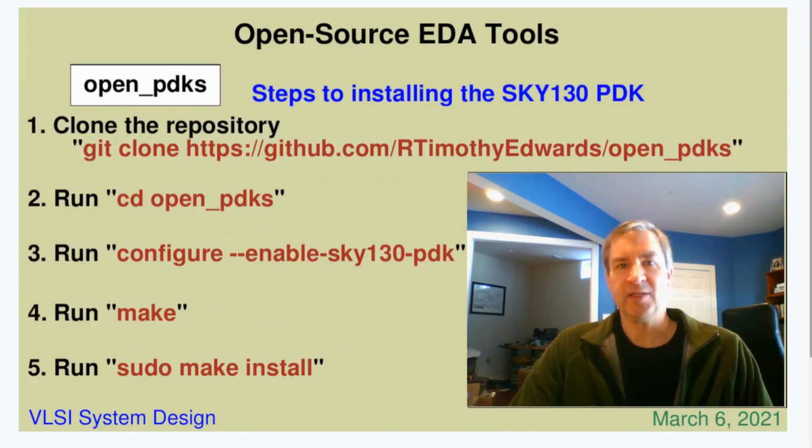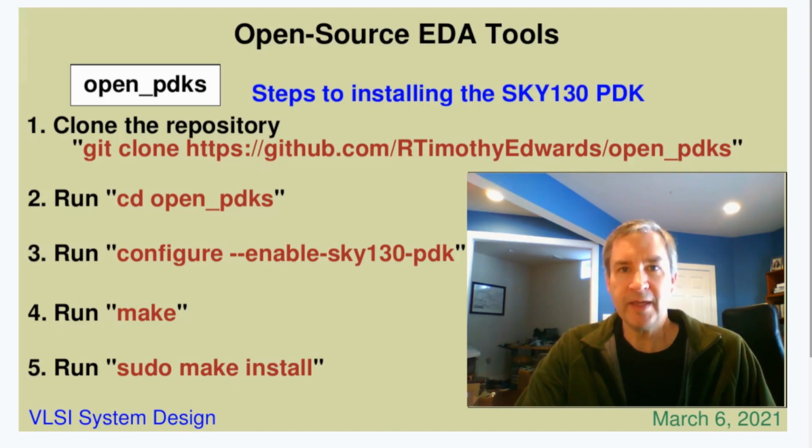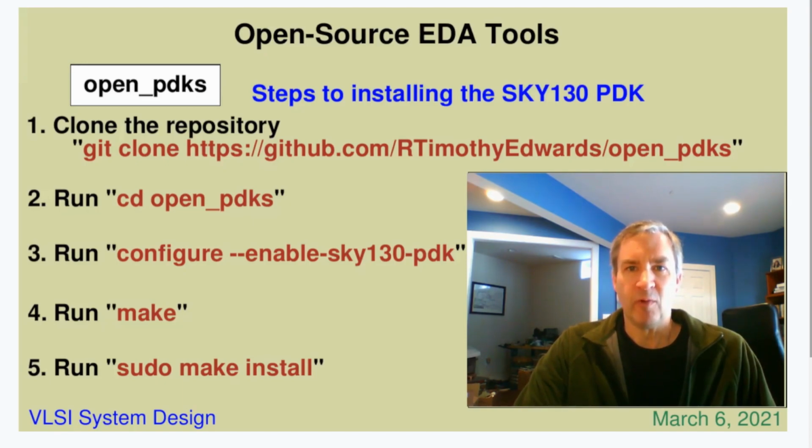Here's how OpenPDKs works. I have gone a long way toward simplifying the whole thing recently so that if you want to get everything installed and set up from scratch, all you need to do are the simple steps of 1. Clone the repo, 2. Run configure, 3. Run make, and 4. Run make install. Since OpenPDKs is still ostensibly supposed to support arbitrarily many processes, specifying the process to install in the second step is needed, but everything else should be worry-free. For the second step, use